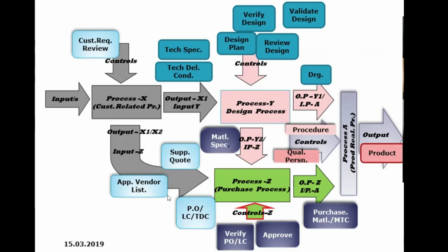So if all controls are perfectly managed, the product will be correct. If you are not buying the material from the approved vendor, approved supplier, QC and the final stage can come and say, "Sorry, we are not accepting the product because the plate itself was not purchased from the right and approved source or approved supplier." If the drawing is not approved, they said we don't accept it. The drawing was not approved. How did you make the pressure vessel?